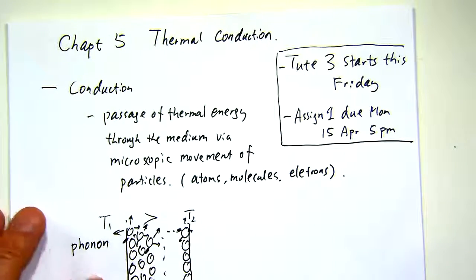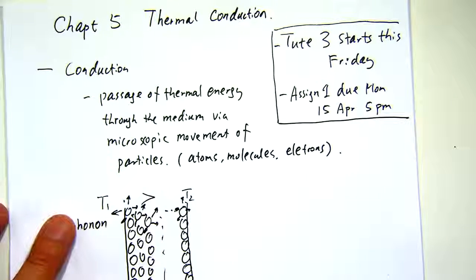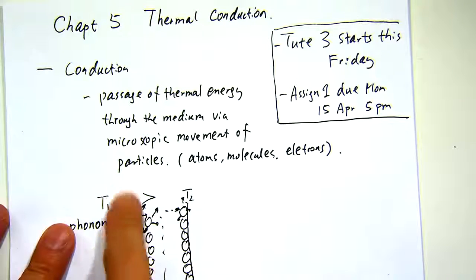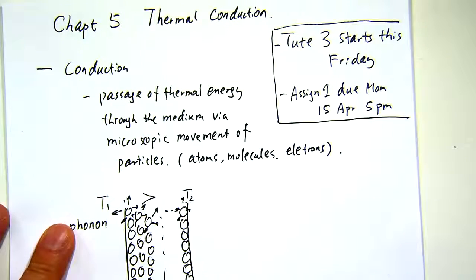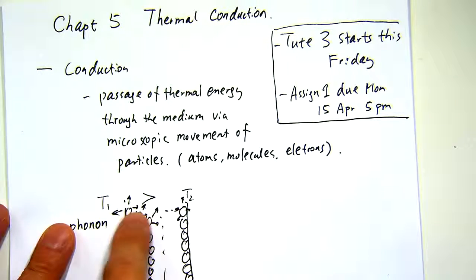So in this case, you can certainly consider that the heat transfer or the energy transfer due to the collision process is not elastic, which means along the passage that the thermal energy is being transferred, not all the thermal energy at this surface will be transferred to the other surface. So some of it gets lost just because the collision between the atoms is not 100% efficient, right? The collision cannot transfer all the energy there.